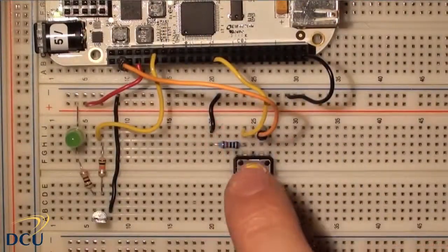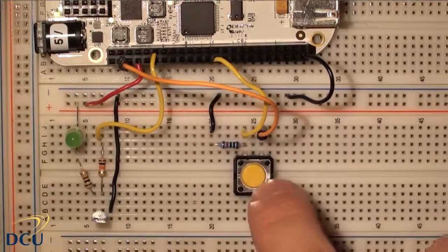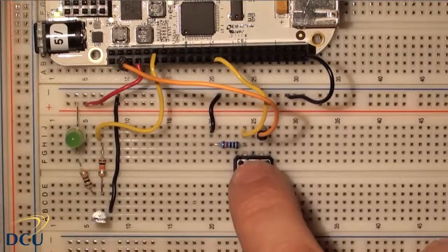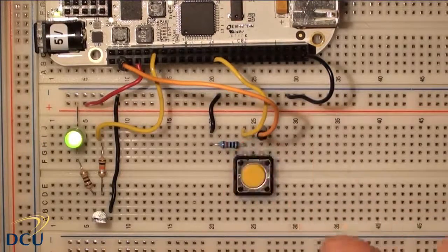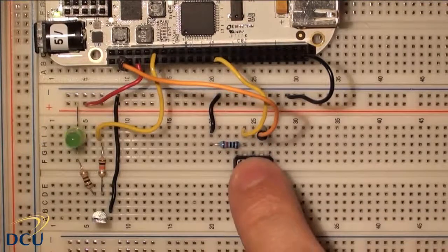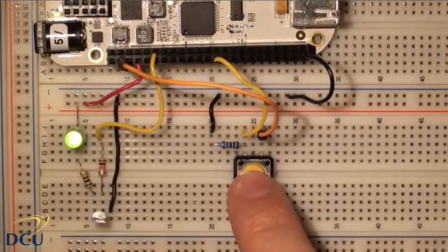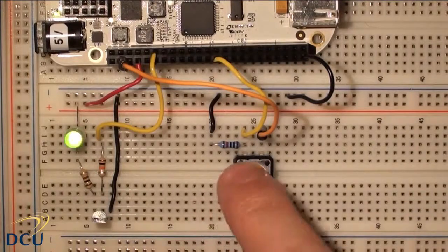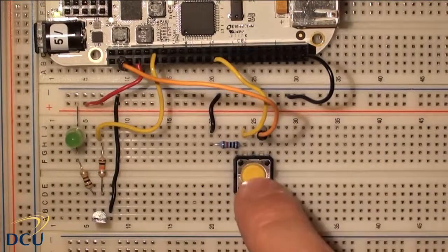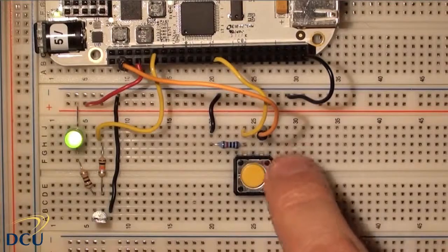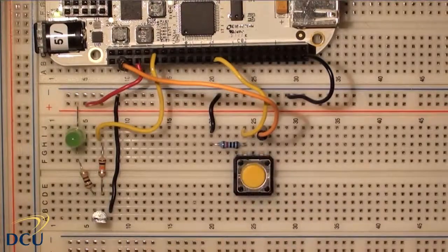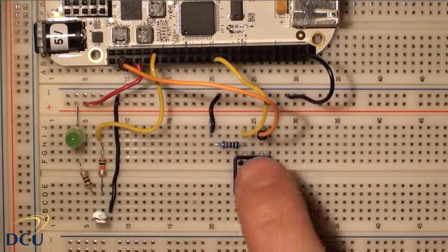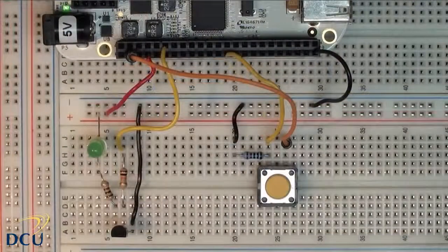The eventual aim of this video is to demonstrate what looks like a very simple circuit, but is actually surprisingly complex. I want to write a C/C++ application that when I press a button, an LED toggles, going on if it's off or off if it's on. The button will be connected as an input and the LED as an output. I'm also taking care that I drive a very small current through the GPIOs using a transistor to switch the LED in this example. To do this I have to deal with polling, which I will cover at the end of the video. This is the final circuit that I've wired.